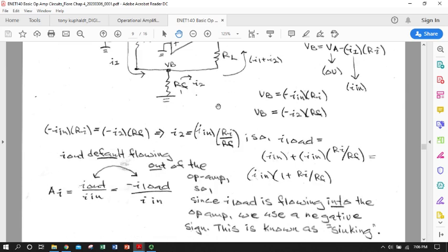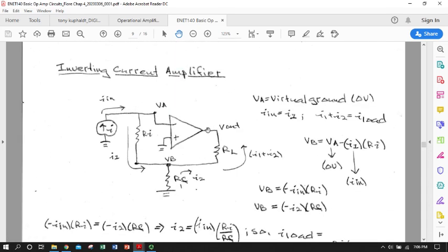We'll probably be interested in the current flowing over the load resistor, which will likely be I1 plus I2, which is I out. It's I over the load. Typically anything we're concerned with on the output is going over the load. So I1 plus I2 is going to be our effective output current. I1, or In, is our input current. So we're going to want to define I1 plus I2 in terms of our feedback resistor network, because that's what we can define. Okay, so let's start walking through that.